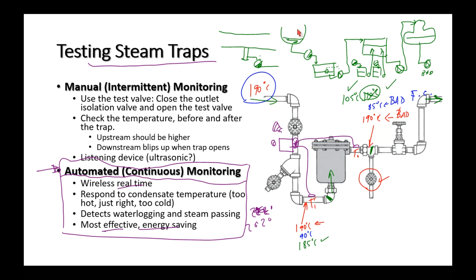Okay. Let's see if this can answer your question a little bit better. This diagram that I've shown of some kind of a heat exchanger has a pool of condensate in the bottom. Normally we wouldn't see that. I just use that for illustration purposes. Think of this thing as being all full of steam. Now, as the condensate forms, it will run down through the pipe and into the body of the steam trap.